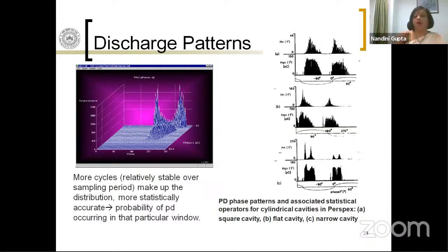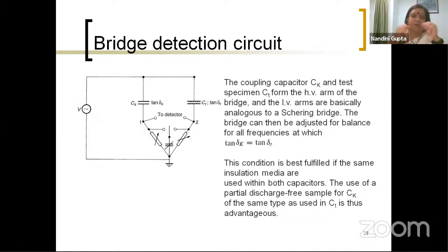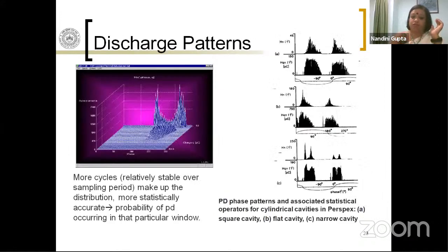For example, in the video I showed you, we are not going to get the same PD when the PD is through the filamentary channels and then suddenly the PD causes the channels to become thicker. In that scenario, we had a many-fold increase in the PD magnitude. So the PD pattern is not going to remain the same if the stress mechanism comes into action or more and more other PDs begin to happen.